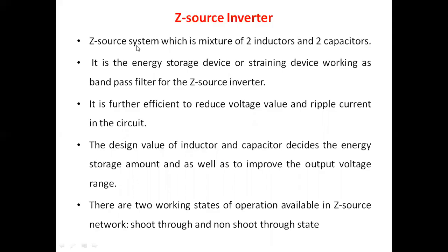Generally, the Z-source inverter is a mix of two inductors and two capacitors connected in an X shape. It is used to boost the inverter output voltage with the help of this inductor and capacitor design. Based upon the size and design of the inductor and capacitor, the output boost level can be decided.